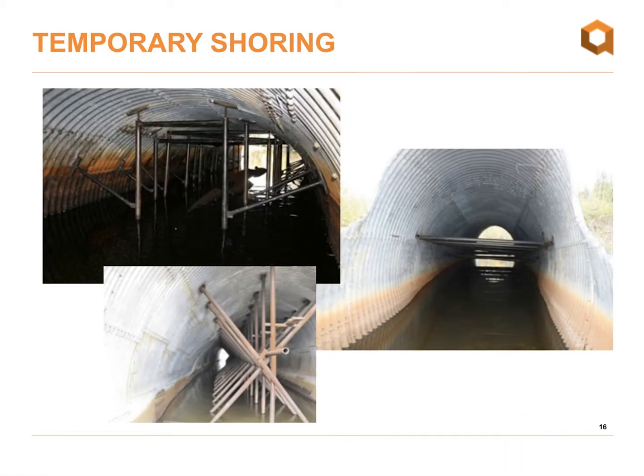So temporary shoring is, just as it sounds, a temporary measure. Essentially, if you've identified a structure that's near failure, or there's a significant concern about structural integrity, this is an option just to extend that service life an extra 1 or 2 years while you plan for a temporary rehabilitation system or a full replacement. So we might have some sort of shoring, jacking, whatever the case might be, just to ensure that we have a structure that continues to carry its load capacity.